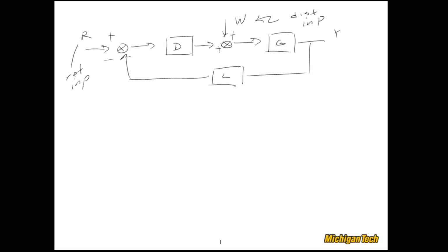What system type allows us to do is, in a very simple way, classify how the system responds in steady state to reference inputs and disturbance inputs. And it does it in a very compact manner by simply describing that in terms of integers. The thing that we're going to focus on is the polynomial order of the inputs.